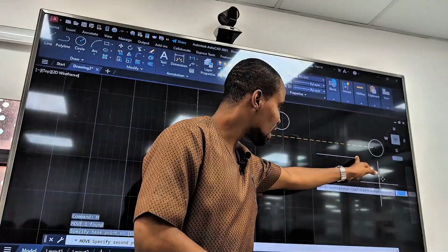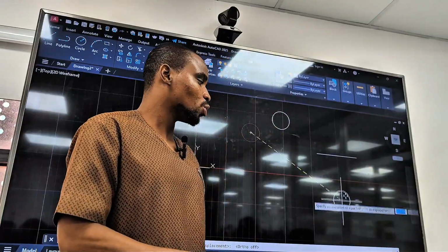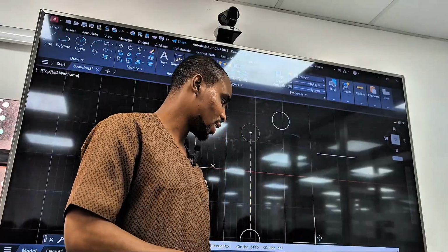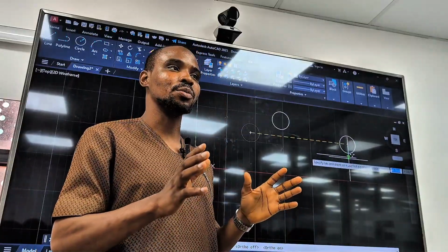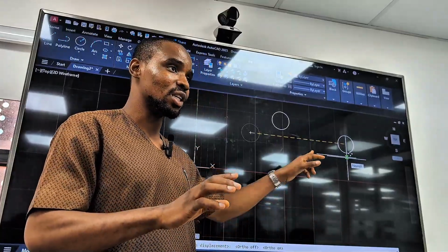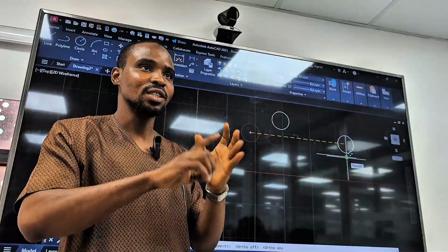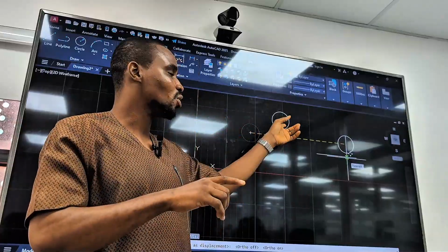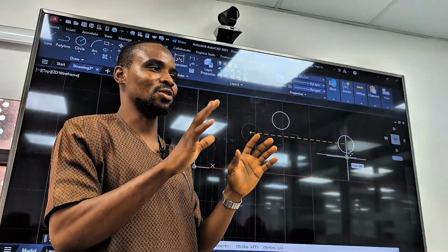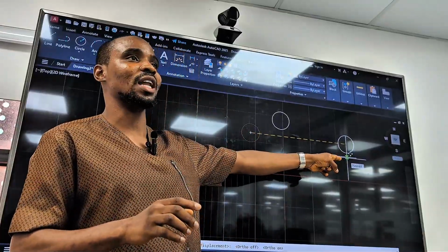So then align it with the center. Move it very close. You don't need to turn off F8, and you don't need to turn it back on. So this is why snap point is very important. Even without your F8, you can still achieve the alignment because your snap point is on. Your middle point, your center line, the middle of your center, everything is on, right? So you don't have to fear that it's not going to align.